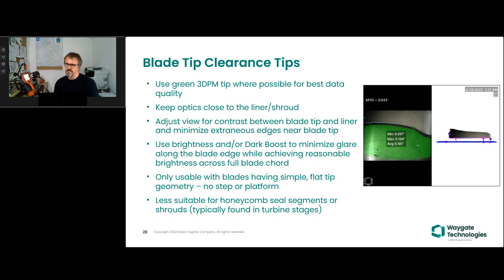As Clark was saying, really make sure that you've got the optics tuned, the optical field tuned to the scene that you're looking to detect. So practice, in this case, for blade number 1, in terms of getting your probe positioned so that you've maximized the scene that you want to measure before engaging the 3D phase measurement capture. I'll be running through a demo shortly on the borescope, but just going through some of those tips here before going through the demo.